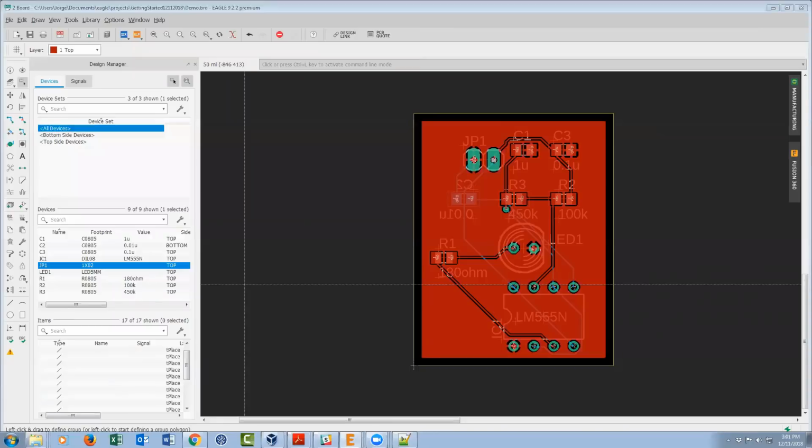Key point for everyone. Okay? When you're working with Gerbers, once you generate them, it's always a good idea to view them in a Gerber viewer before you send them out to the board house. Doesn't matter what the Gerber viewer is. You can use GerbV, you can use ViewMate, you can use GC Preview, CircuitPeople.com, whatever. It's always a good idea to verify the Gerbers through a third party, because no one's perfect, right?